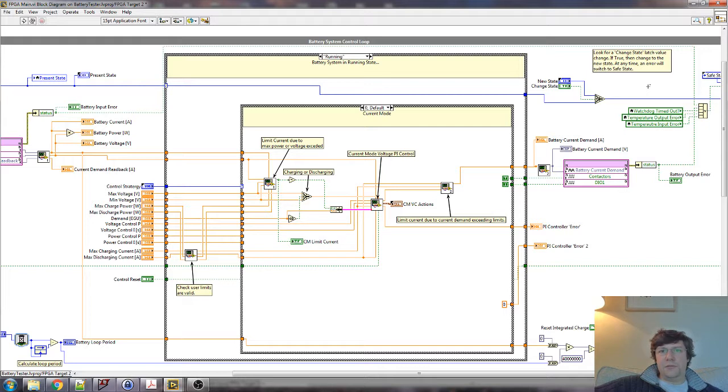They were usually modules, so we were looking at 12 volt setups or 48 volt setups, which is strings of 12 or strings of 12s. So we weren't doing a lot of cell testing like you might find a Maccor or a Digatron setup for, where you've got 32 or 64, 128 channels of 0 to 20 volts with 0 to 5 or 10 amps per channel.